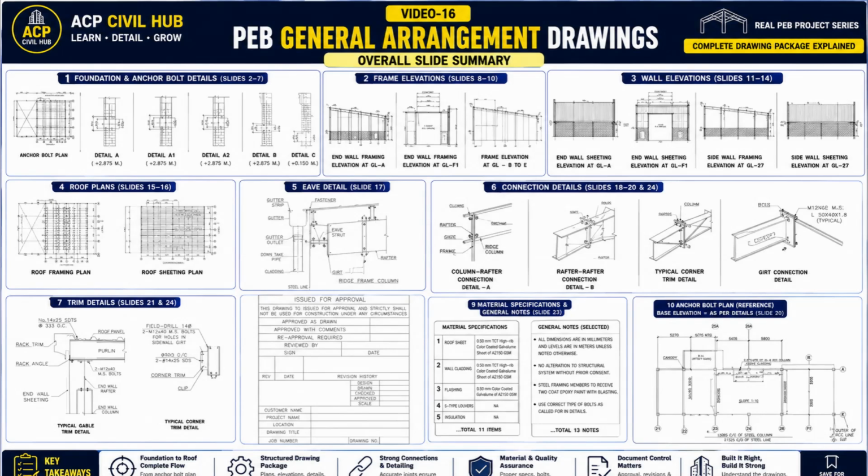Now, let's quickly summarize what we have learned from this complete PEB General Arrangement Drawing package. We started with the foundation and anchor bolt plans, where the exact locations of columns, grid lines, dimensions, and anchor bolts are established. Then, we reviewed the primary structural framing, including the end wall frames, columns, rafters, and different frame elevations that define the main structural system of the building.